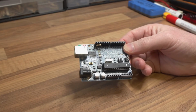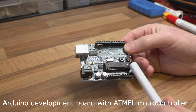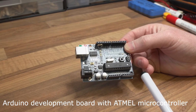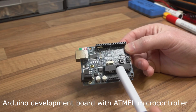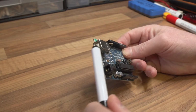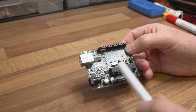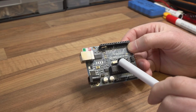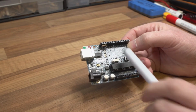Well, you may have come across these before. This is an Arduino development board, and it's got a single microcontroller on it. Now this is where we start talking about microcontrollers. There isn't actually that much else on the board except for a little USB interface chip here. You've got power in, and you've got a crystal here for the clock. This particular one has a 16 megahertz crystal on it, and everything else is pretty much pins.